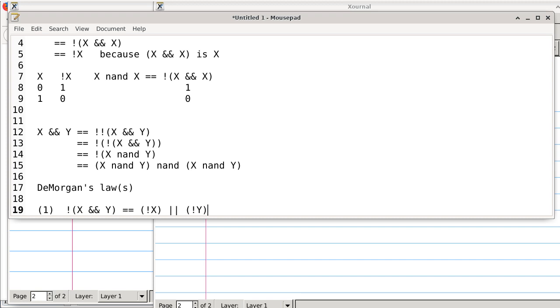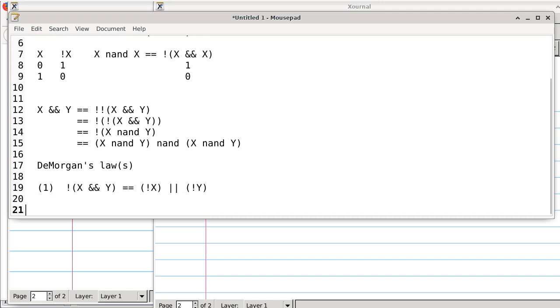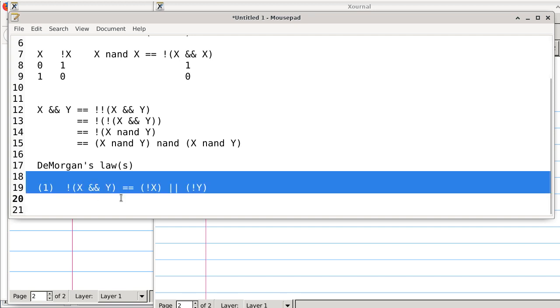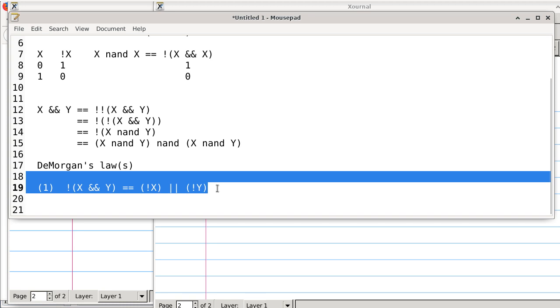Boolean algebra would be a little bit harder in this case because you're trying to prove one of the axioms in Boolean algebra. Truth table, very good. So we can actually prove this using a truth table. I'm going to do it one more time, just so that we get another exposure of how a truth table works. So when you look at this particular equation, how many variables are involved? There are two variables. X is one and y is the other one. They are independent. There's no interdependency between the variables.